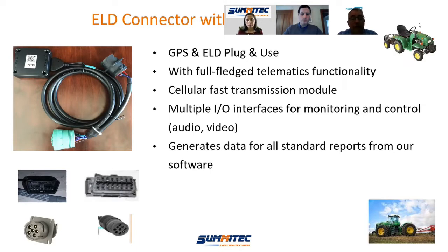The other option is to have a Y cable that allows the customer to keep the diagnostic connector for its intended purpose, which is diagnostic, but also hide the tracker below the dash or inside the cabin a little bit better. And that's especially good if you want to use the tracker for theft recovery.